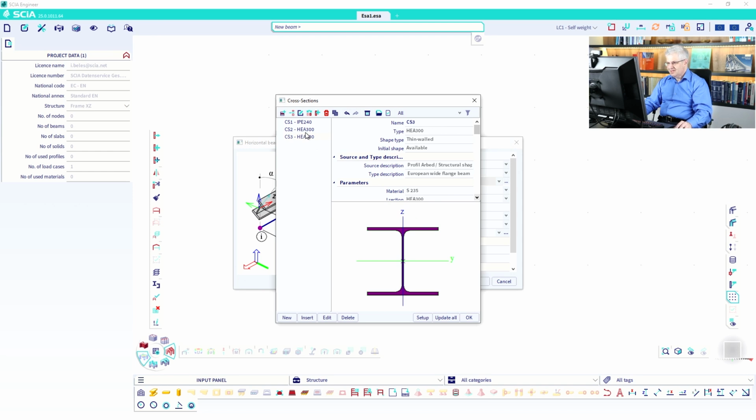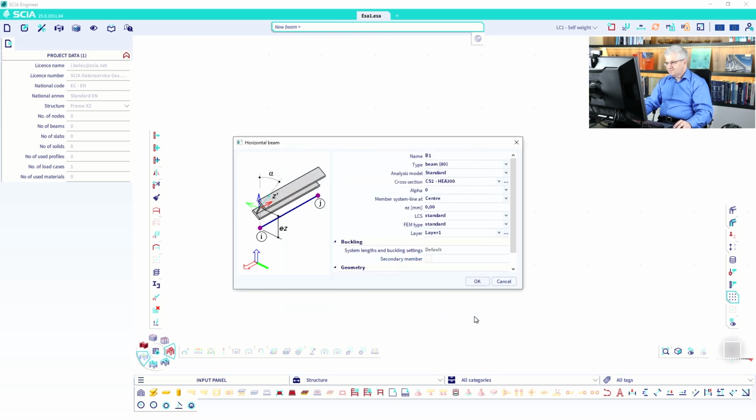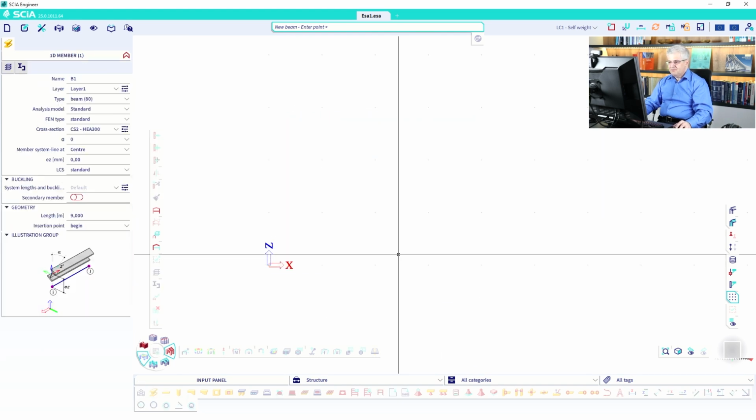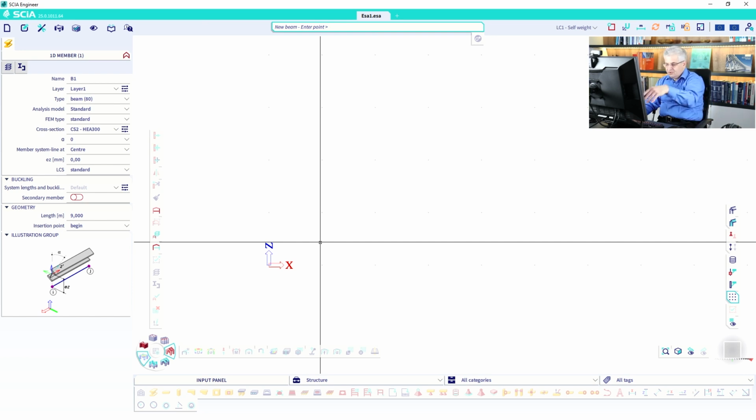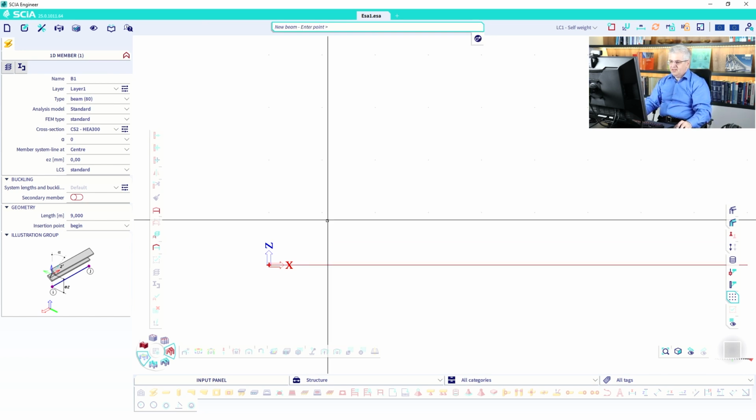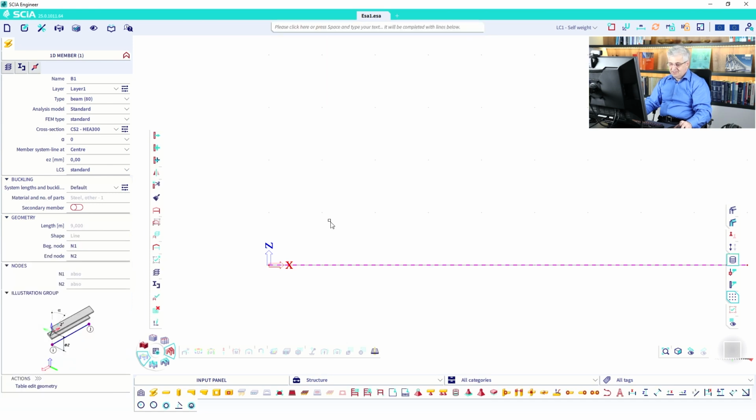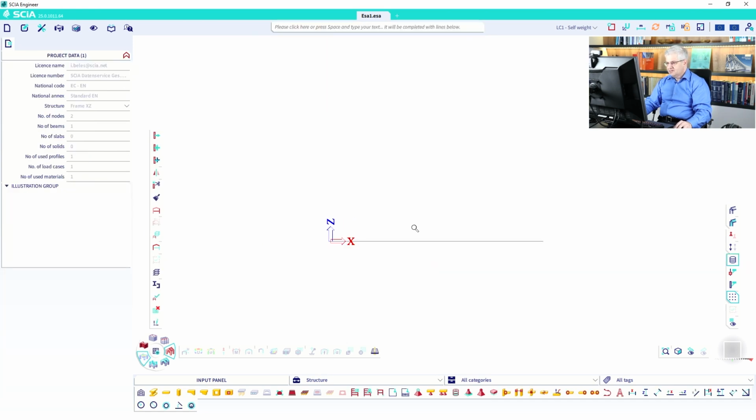I did it 2 times, sorry. I have to talk less. Okay, so it's 9 meters, that's all. For the beginning, you can click anywhere on your screen, but simply write 0, enter, then it's the 0 point, and escape, escape, escape until it's not violet.